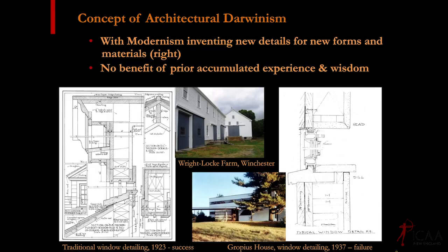Shows basically that this was figured out. We knew how to do wood-framed clapboard buildings. We knew how to do doghouse dormers. And I could spend a whole hour talking about how thoughtful all these details are at the micro level, just the way everything overlaps, the drip edges, the flashings, the underlayment, everything about it is incredibly well thought out, and you would do very well to build a building just like this today. They really had it down.